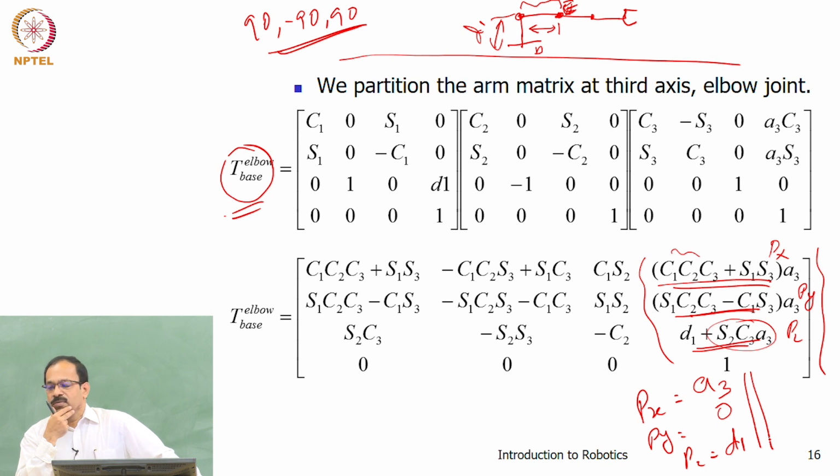No. See, you should understand one thing. Theta is a variable. Alpha we are defining as the rotational axis, how the rotational axes are oriented. Okay. So you are saying that you have one rotational axis z, and how this rotational axis is related to the next rotational axis is basically the alpha. That is how we are defining alpha, the angle between two joint axes.